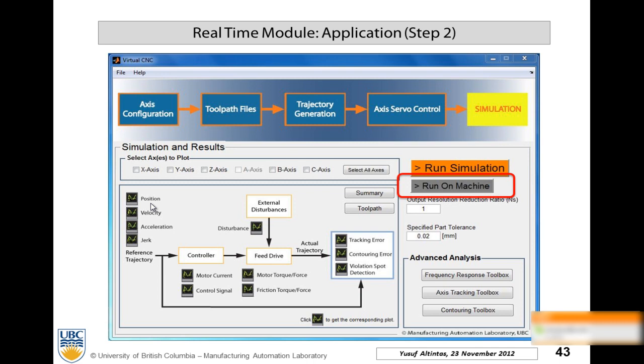We will identify servo dynamics. That's one topic. We are doing these things, but we have to do this on a real machine, on a commercial machine, with limited access to CNC. We are using Servo Guide, right? We have Fanuc's Servo Guide. With the Servo Guide, Fanuc gives you the frequency response function of the velocity loop without the controller, and you can read the controller from the panel. Then we can build the controller, but they do more than that.